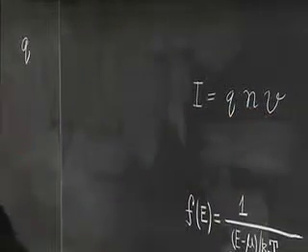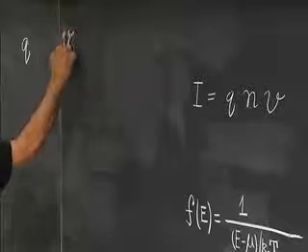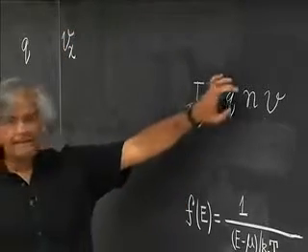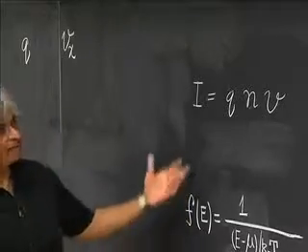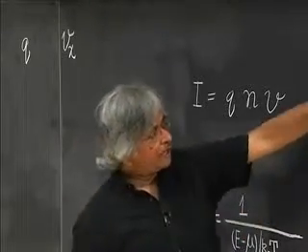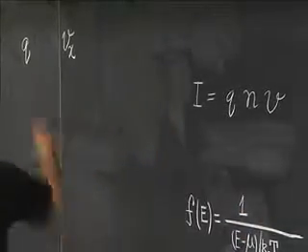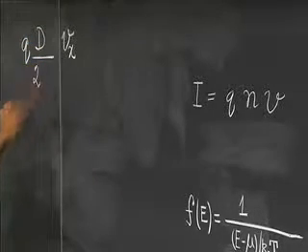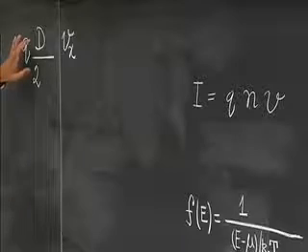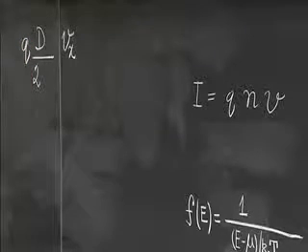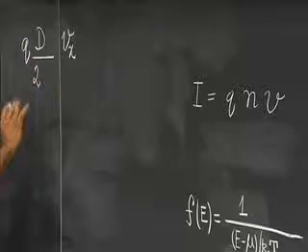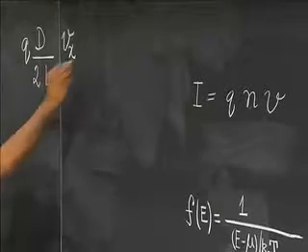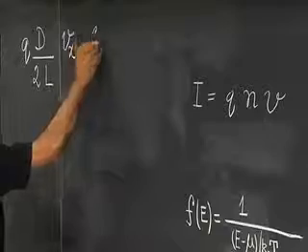So you could write the velocity v of x, that's in the x direction, and this electron density, that we could write by saying that we have the density of states is D over 2, because I only want to consider half the states, the ones that are going from left to right, and I want the electron density per unit length, so I'll put a length here, and I'll multiply it by F plus.